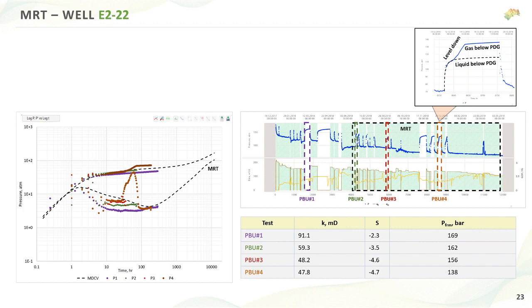Unfortunately, during the production here, we have crossed the line of bubble point, and now as our pressure is falling below the bubble point, we have more and more gas liberating in the near wellbore zone, which creates a two-phase flow in the zone, and the transmissibility is going lower and lower. So this is actually not good. Unfortunately, the water flood here is not as efficient as our clients wanted it to be, right? This is point number one.